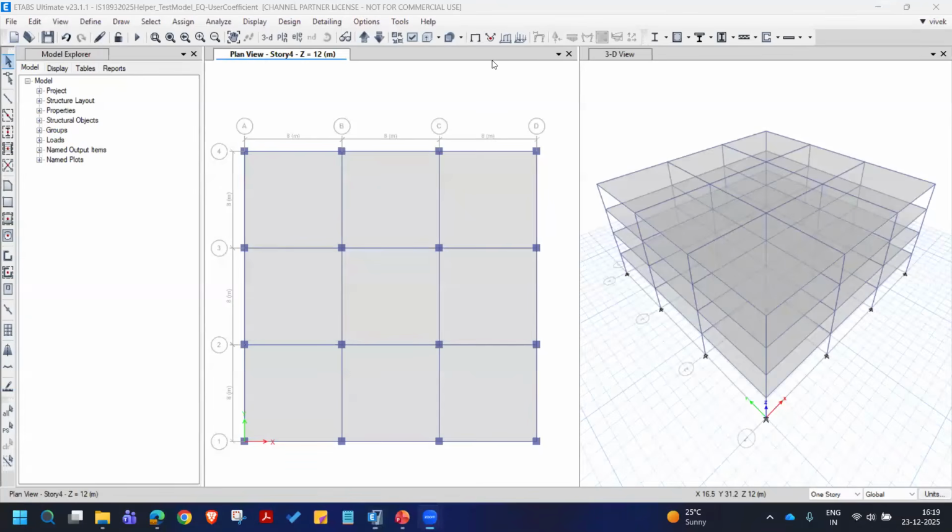Yeah, the comparison of base shear from the old and new code. So it is not about load combination, it is only about the estimation of the input base shear. It is not the member design combination, the estimation of the earthquake force.